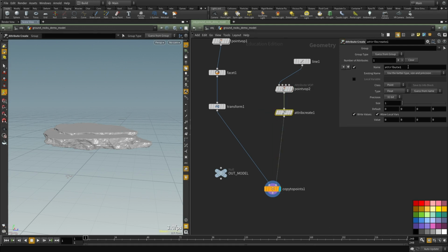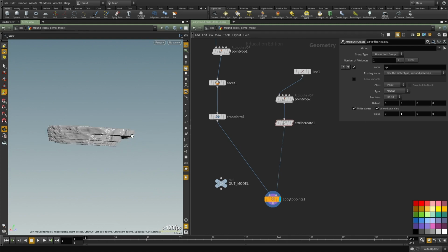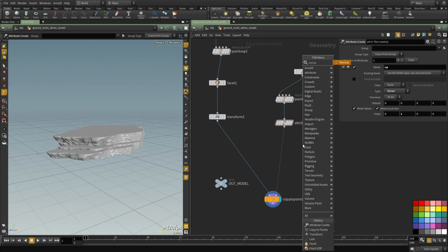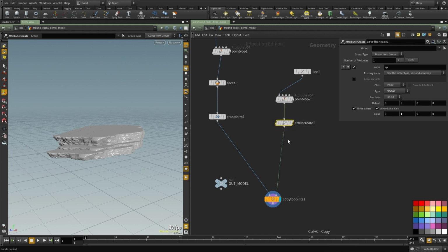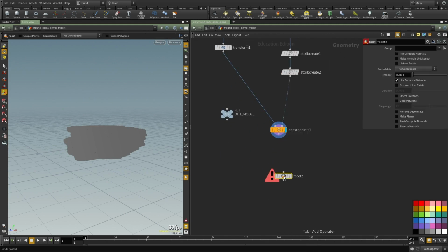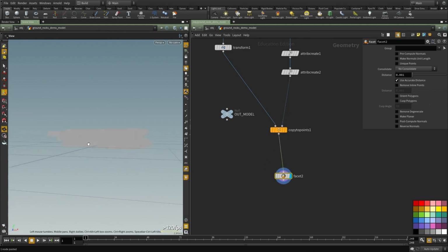So I'm going to use a create node, call this up vector. It's a vector and it's pointing upward. You can see the objects changed slightly, but we still need the normal. So for the normal, I can create another. Let's copy this attribute create. Let's create our normal, and if we give it a positive z-axis, that's the alignment that the copy node looks for. We're going to be getting a perfect alignment, and each object is facing the correct orientation.